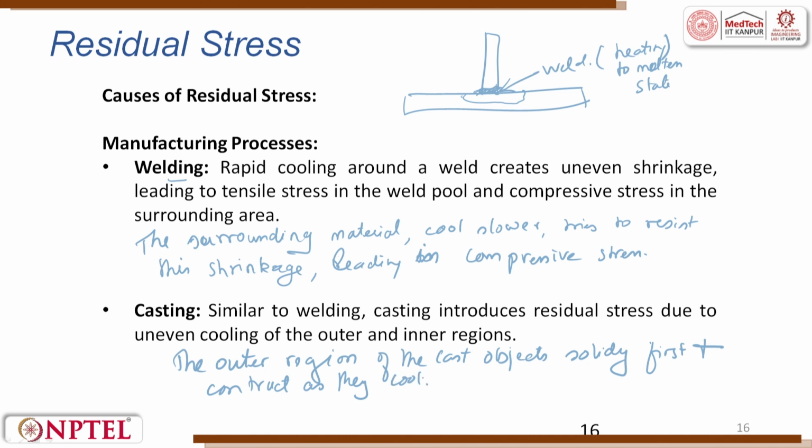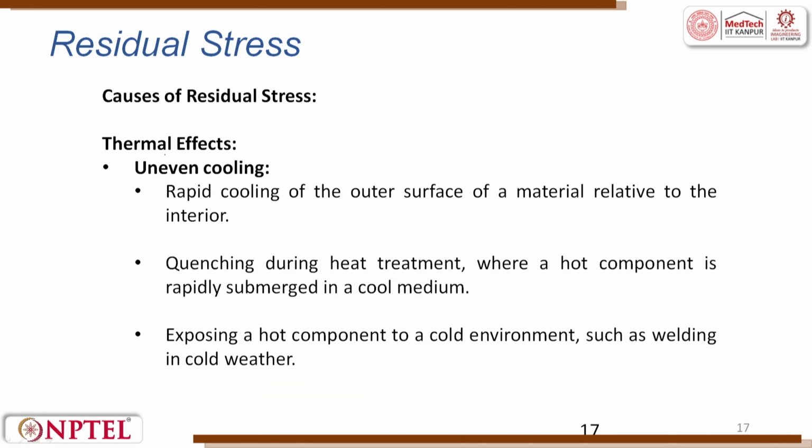Okay. Because of heat, you have this residual stress which is happening. So, thermal effects, uneven cooling, rapid cooling of the outer surface of the material relative to the interior leads to thermal residual stress. Quenching during heat treatment.